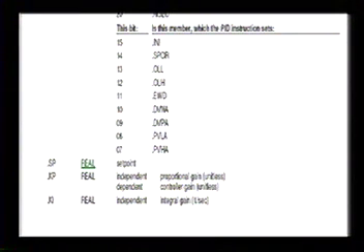The KP, again, is the gain, right? It's a controller gain, and it's a proportional gain if it's independent or dependent. And you've got your KI as a real value, and KI is your independent gain. And again, this is your integral gain. And again, you can actually say, if you made your tag name PID1, it would be PID1.KI, right? And that would be your integral value.